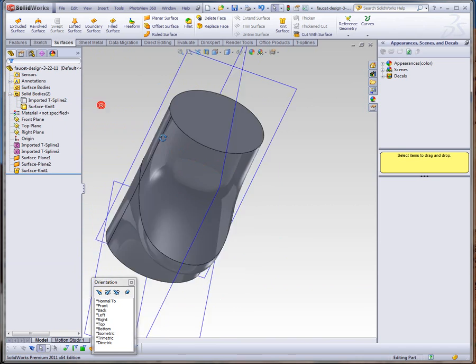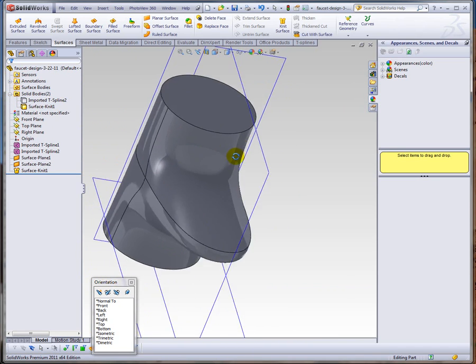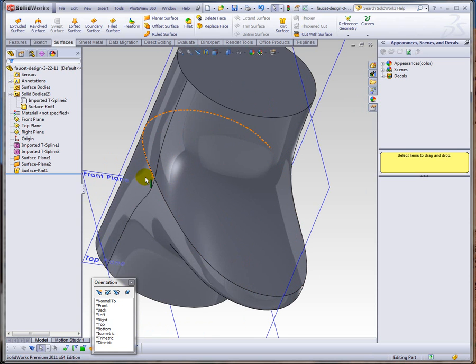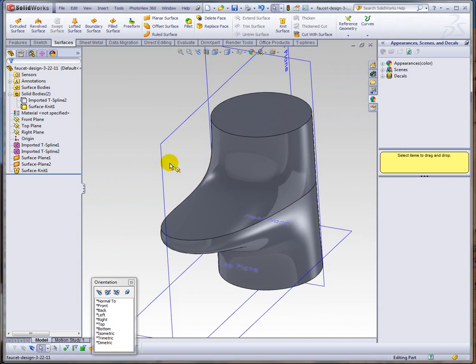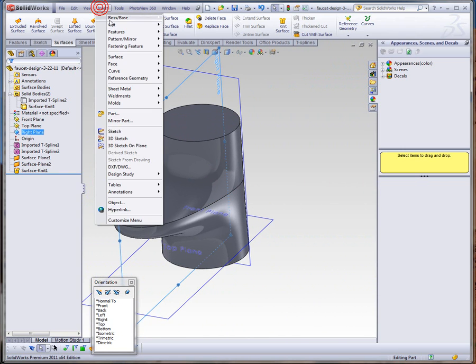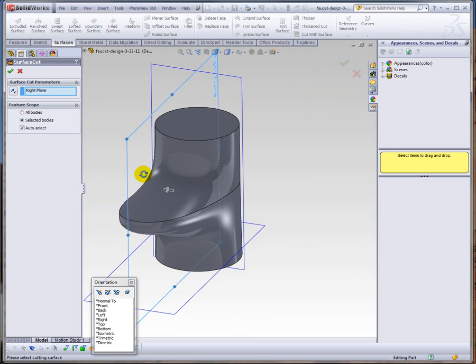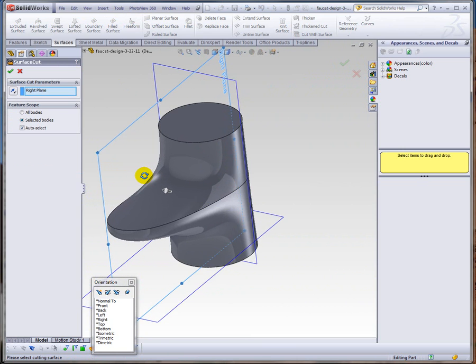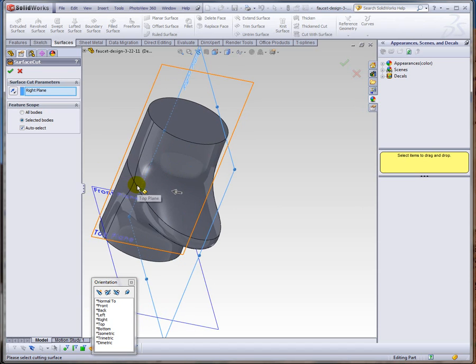But you know what? I see something here I don't like, and that is that I must have pulled something in Rhino here to make this asymmetrical from left to right side. So I'm just going to quickly cut this solid using this face. And let's see, we actually want this side here.